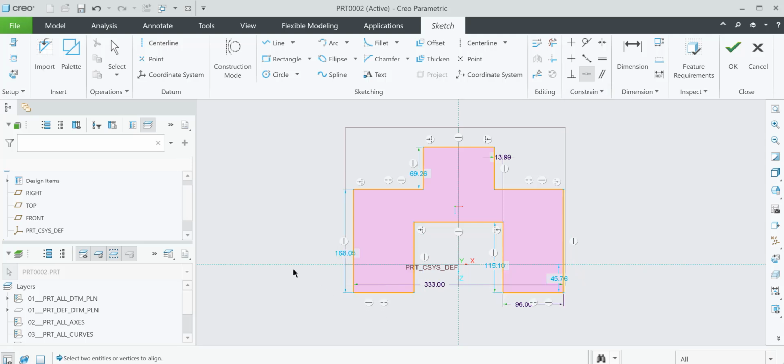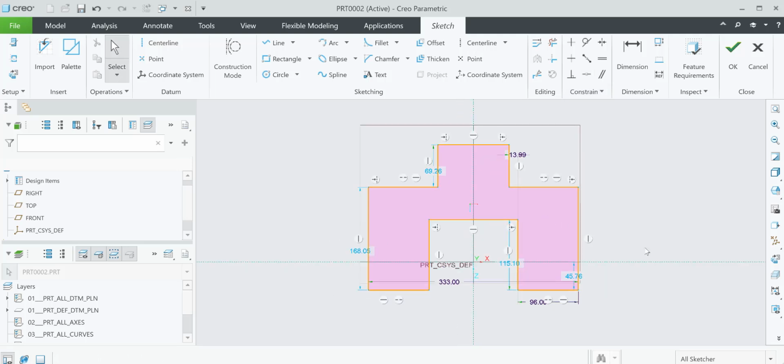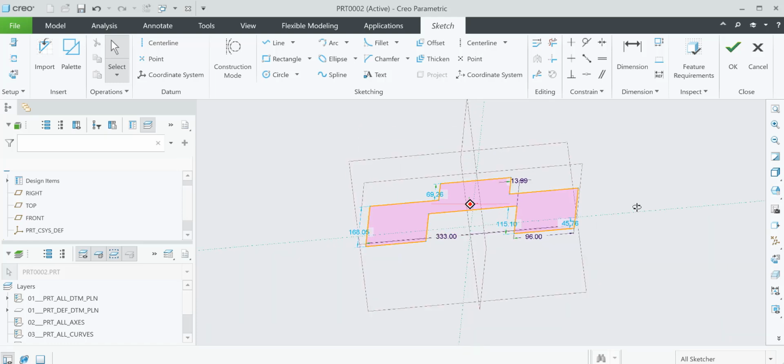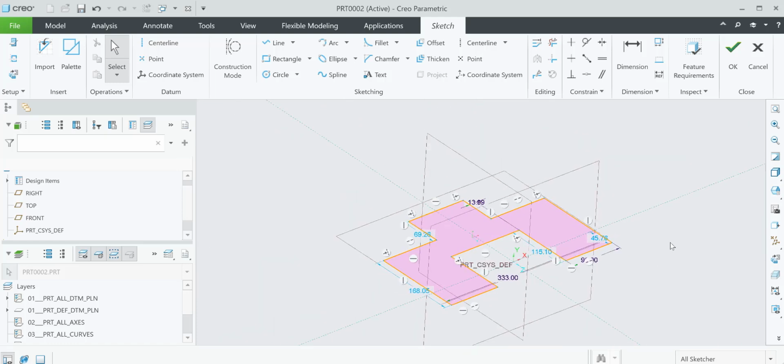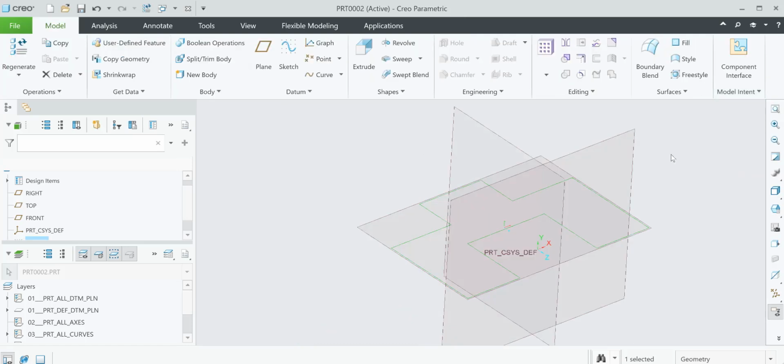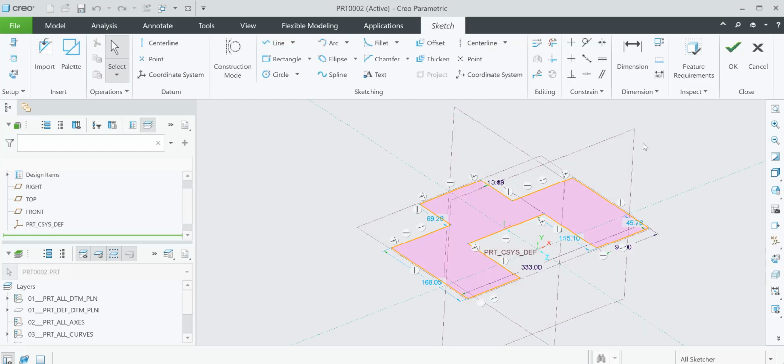It's helpful, not necessary all the time, but if somebody feels compelled to remodel your geometry, it's probably because the datum planes don't line up to anything. So now, what if I redefine this sketch and consider aligning the flat face to the datum? Maybe that's what's significant to my design.